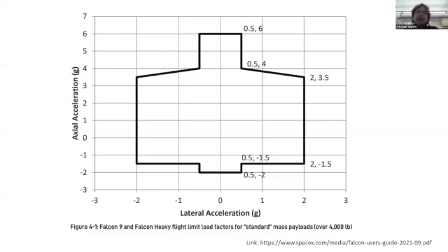But then you see some negative axial accelerations here also, and that's the sort of thing that can happen when during the launch the engines cut off or a stage separates, and the upper stage might decelerate rather than accelerate momentarily, and you may see these negative axial G loads in those scenarios.